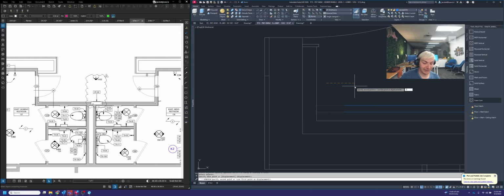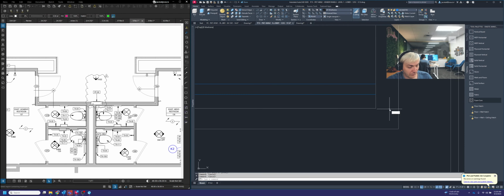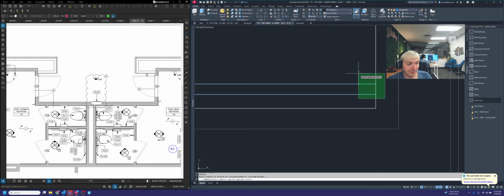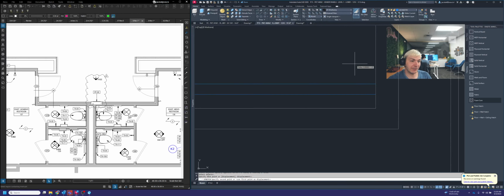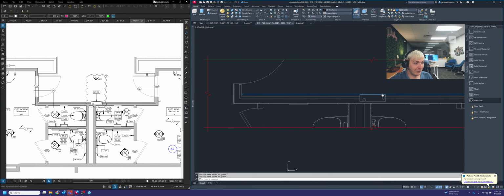It's going to ask you what that distance you want to stretch it to is to be, so 0.75 for 3/4 of an inch. Then we're going to connect the dots. Now let's go ahead and do that over here as well. So stretch, highlight from bottom right to top left, deselect any lines we don't want to move, hit enter, click, and 0.75 over. Okay, so that's the start of our full depth reveals.